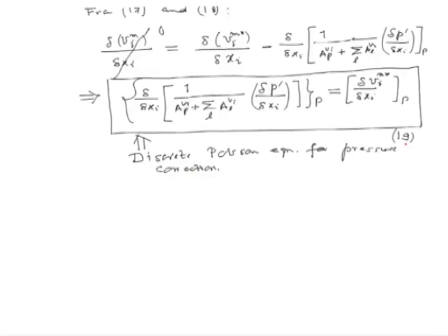Okay, so now we have got all the equations which we need to obtain our solution. We have got our linearized momentum equation which are based on the usage of the values of velocity and pressure field at the previous iteration, and from there we can obtain our intermediate velocity field Vi m star.